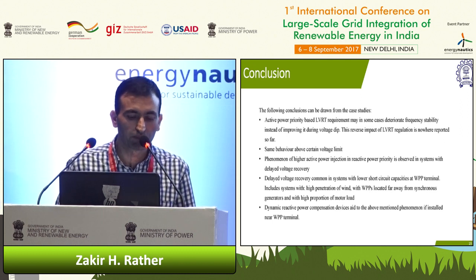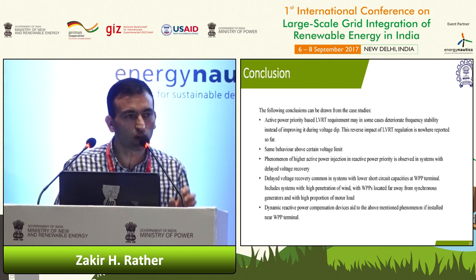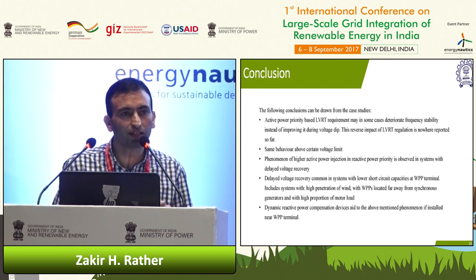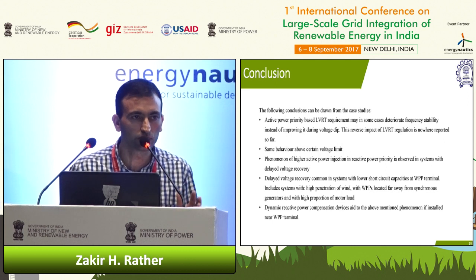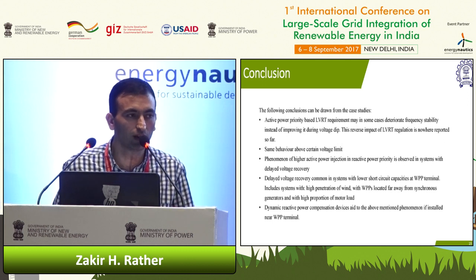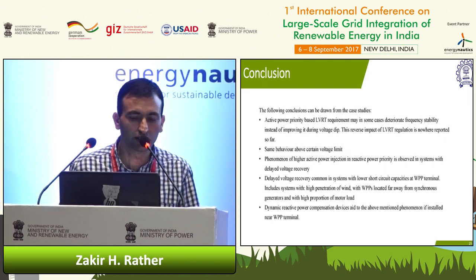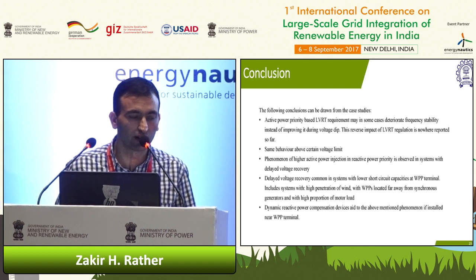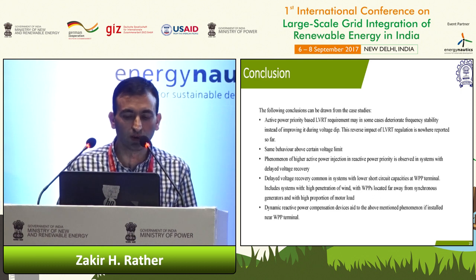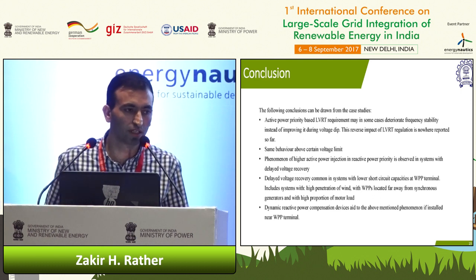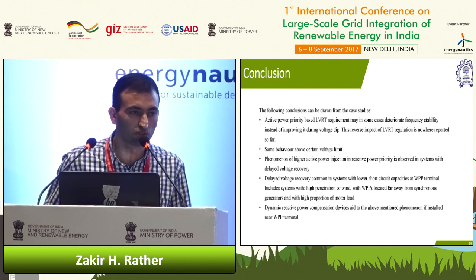So it tries to highlight a deeper issue in this LVRT requirement that we follow across the globe. Two types of LVRT requirements: active power and reactive power. And as the study highlighted, we need to really look into this requirement of active power based LVRT, particularly in some special cases where it actually has opposite results.